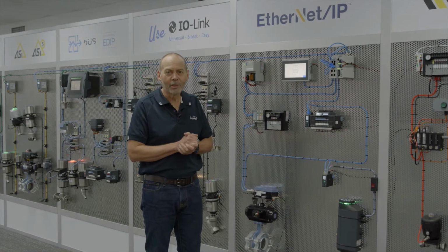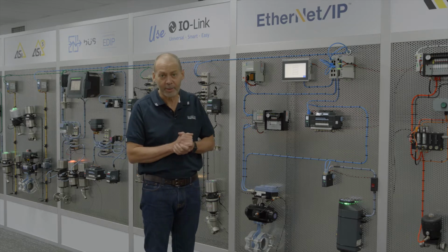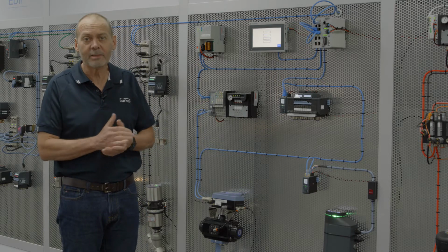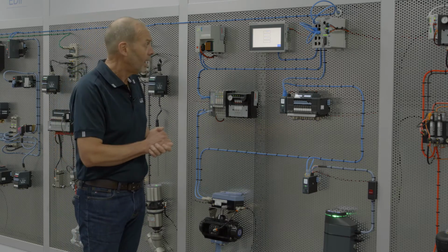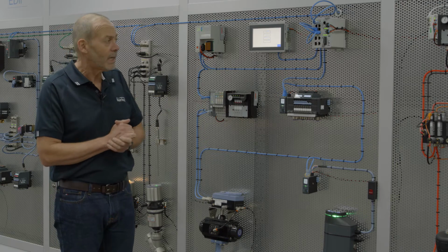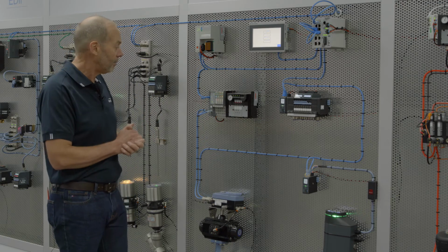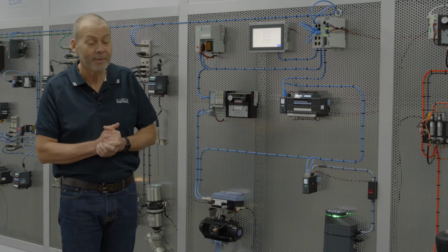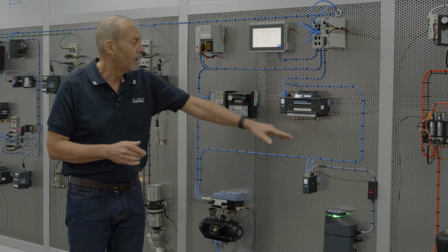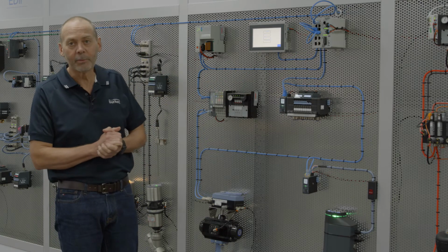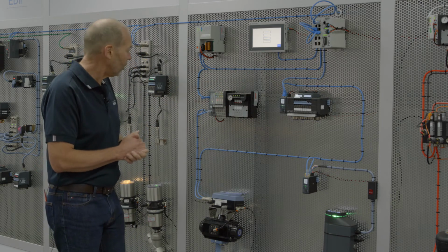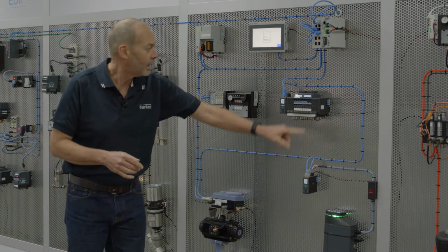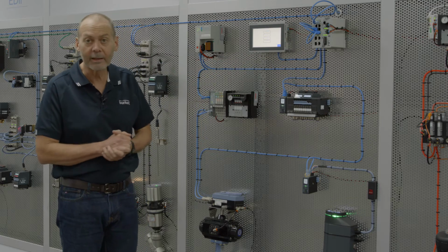Welcome to our digital connectivity video on Ethernet IP. Ethernet IP is also a widely used network protocol, and these days more and more it's being taken to the field. When it's taken to the field, we tend to use devices that are capable of running a Device Level Ring, or DLR, which is a redundant protocol which can hook up to multiple devices out in the field. So with a Device Level Ring, you loop in and out of each device, and you come back and close that ring at the other end.